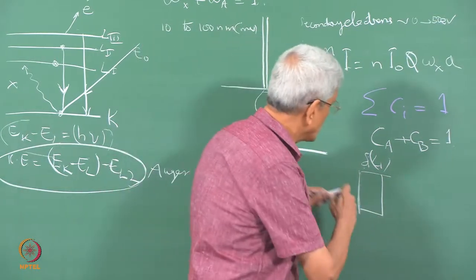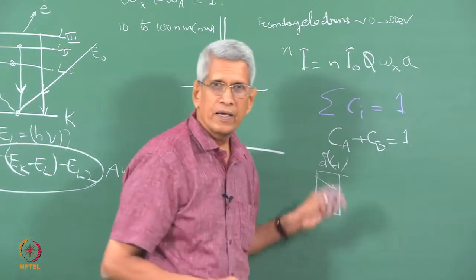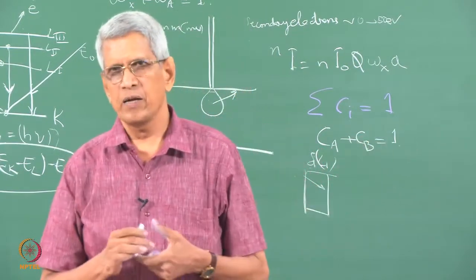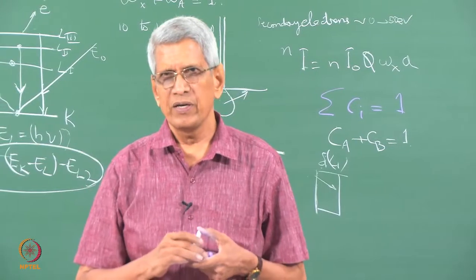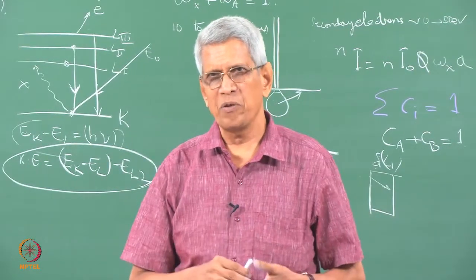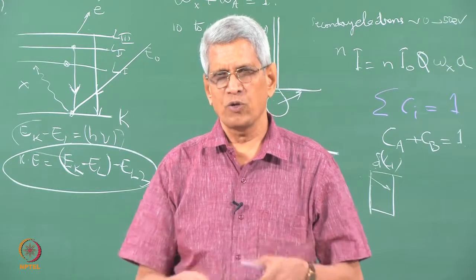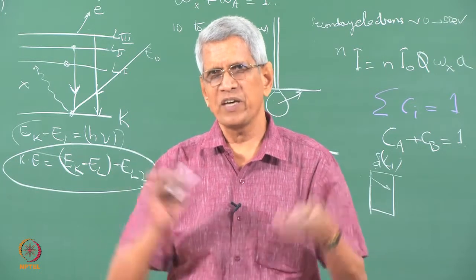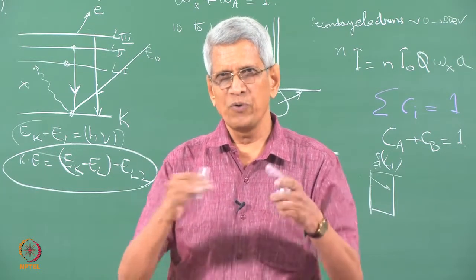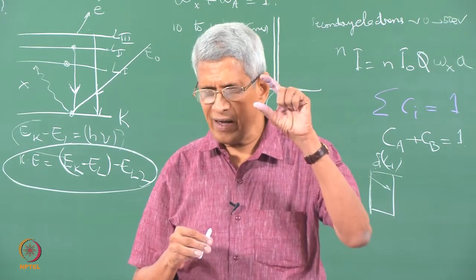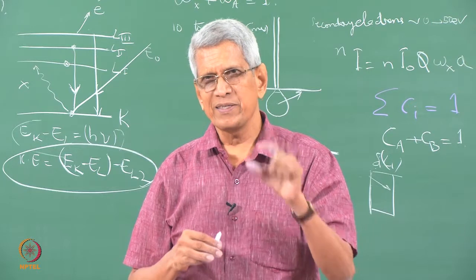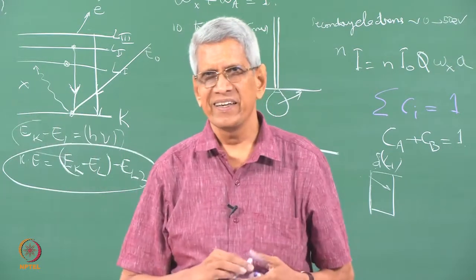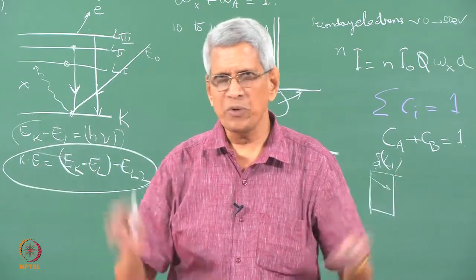As the X-ray passes through this thin region, it produces electron hole pairs, and in the case of silicon that requires about 3.8 electron volt. If you know the energy, we can count how many electron hole pairs will be produced. If they are produced simultaneously, the total charge which we collect is what we count as corresponding to a specific energy. So, if two X-rays from the same element reach simultaneously, that will be counted as a peak with double the energy. That will give rise to another, spurious peak.